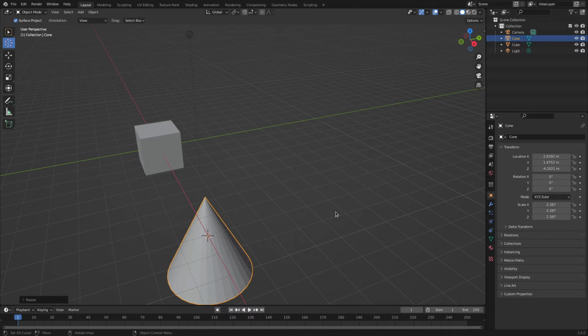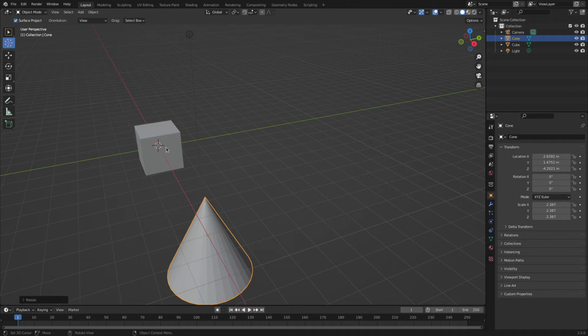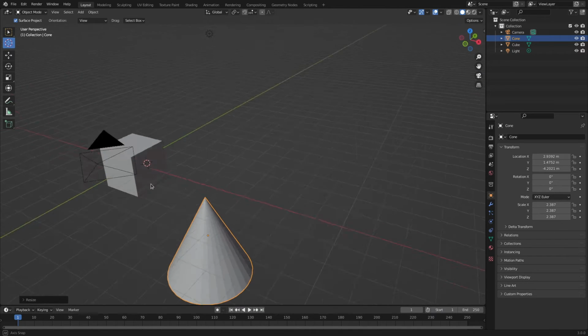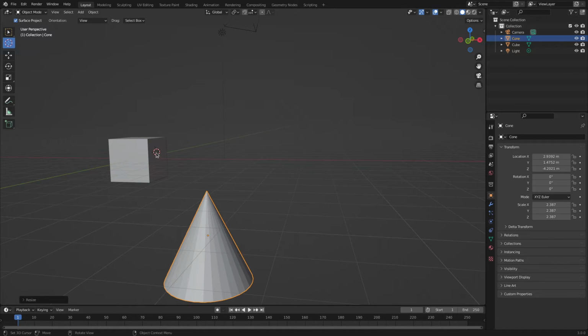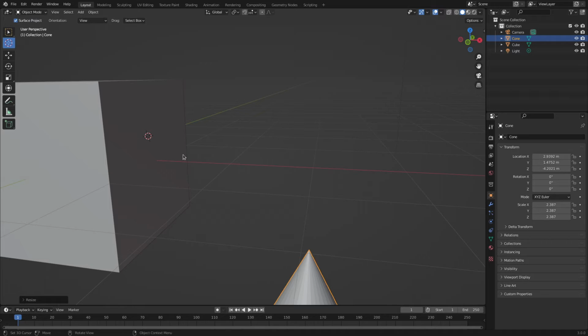Now we're going to go into quad view, which we just barely talked about, because, actually, let's jump back really quick. When you are attempting to set your 3D cursor, often it doesn't get set exactly where you think it's getting set. So if I click there, you would think that's back at the origin of the scene, but if we rotate, you'll see that it's been affixed to the face of that cube, and it's not fully aligned with how you typically would imagine its axes be aligned to the scene.